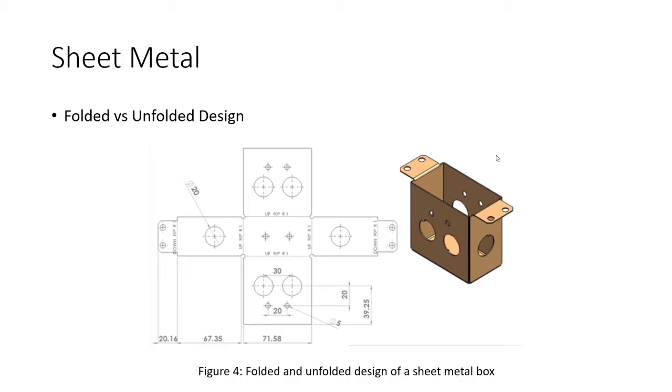So let's say you're using a sheet metal toolbox and created a 3D design like this. Once you're done, there is an option called unfolding or unrolling. If you use that, it will create this flattened design. And this is the design that goes onto the manufacturing floor. Basically, the machine shop guys use this design to cut away the exact portion of metal from the sheets so that you can later on use the bending tools to create this 3D object.